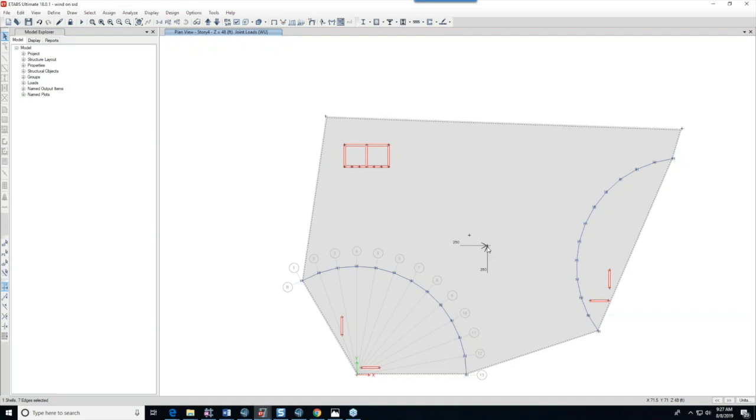Just recently, a question came in. An engineer had a rectangle, and he had assigned user-defined wind loads on a semi-rigid diaphragm, and was wondering why he was finding a huge amount of torsion. Well, the closest joint happened to be a significant distance away from the center of the diaphragm, and it's the next closest joint the program could find, and it was inducing quite a large eccentricity on the applied load. So be a little bit cautious.